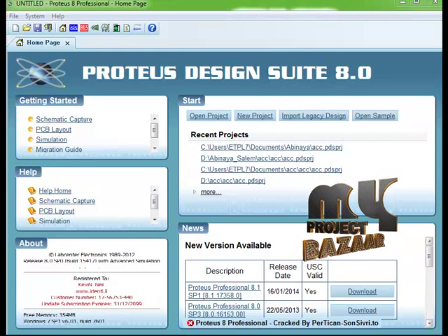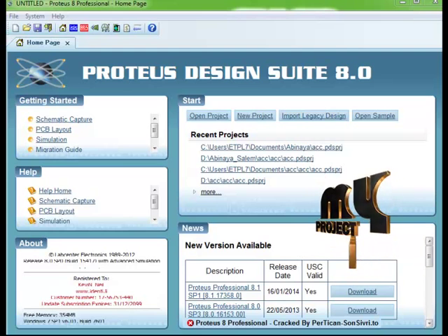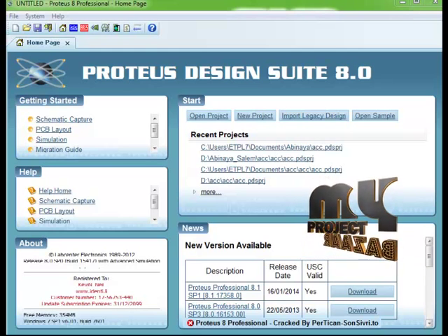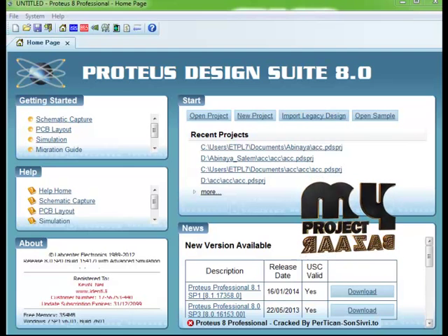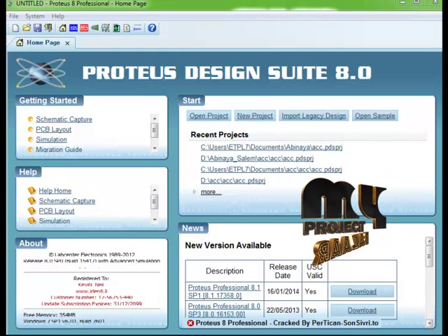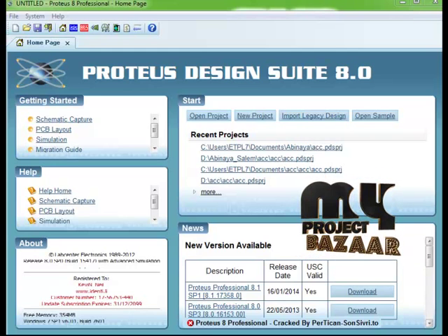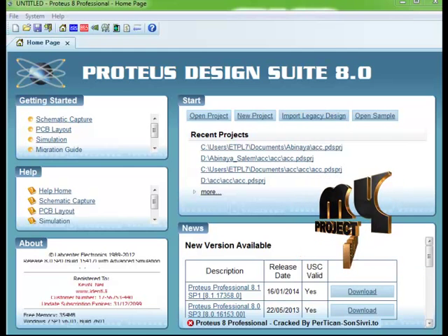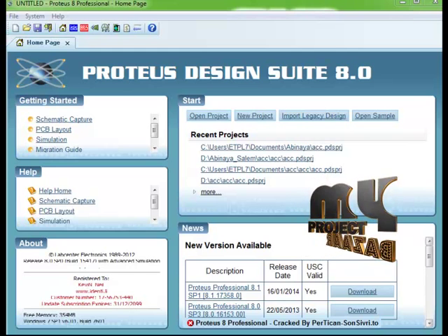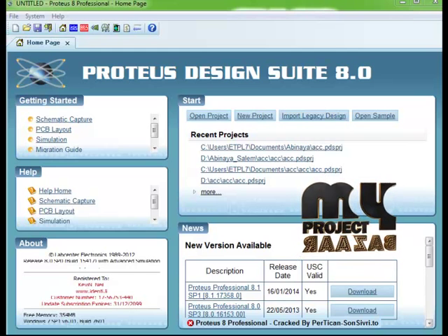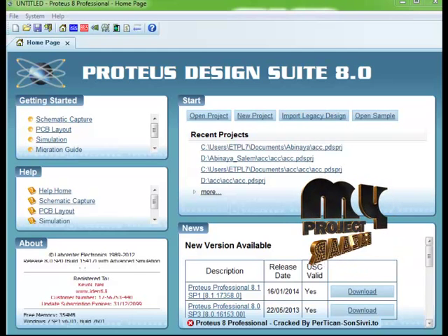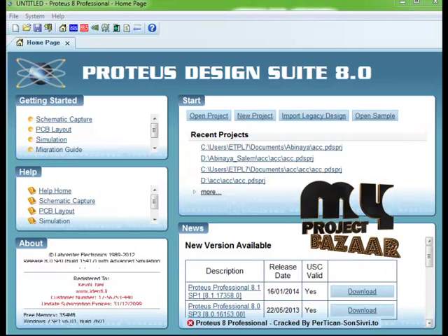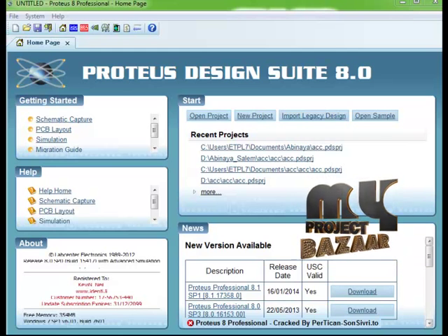After the PIC microcontroller design, we design the MAX232 cable for the connection purpose. The MAX232 cable only links the microcontroller design and the result part, that is the display part. The MAX232 is an IC first created in 1987 by Maxim Integrated Products that converts the signal from an RS-232 serial port to signals suitable for use in TTL compatible digital logic circuits. The MAX232 is a dual driver receiver and typically converts the RX, TX, CTS and RTS signals.